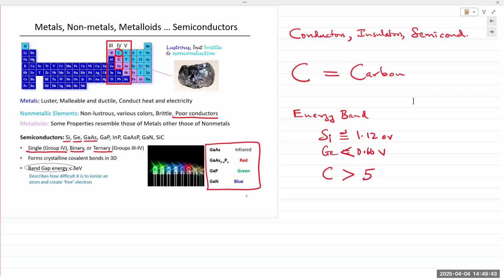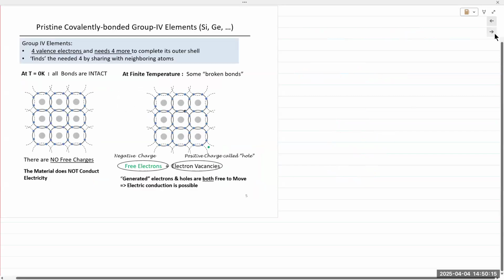This process is known as chemical vapor deposition, CVD. Gas comes in, you adjust the pressure and the right temperature, and it decomposes into carbon atoms. You have a seed material on a sample wafer. Those carbon atoms attach to the seed material, and now you have a diamond film and you can grow diamonds in the lab. That's basically lab-grown diamonds. Again, semiconductor technology. And that's why carbon is not a semiconductor.